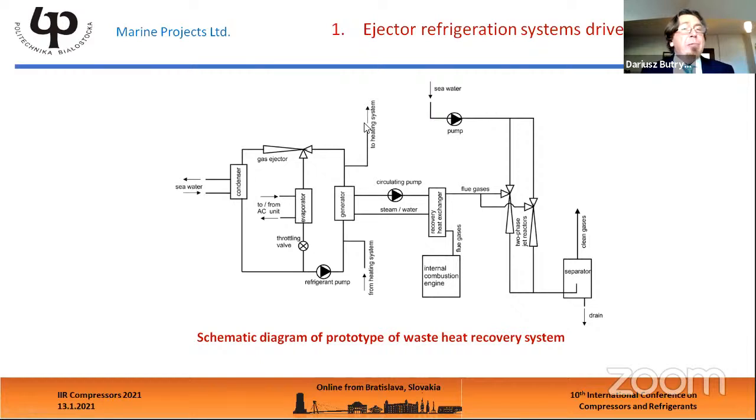So it is composed, well, we are doing the entire exhaust system. This system is composed of a diesel engine, and first we should build a waste heat recovery system in order to recover the waste heat from the flue gases. In our case, maybe it is a unique situation, but we have applied a water steam recovery system. It is really operating in marine applications, because due to safety reasons, you may not apply just flue gases to drive the system directly. And this is our ejection refrigeration system. It is our design of waste heat recovery system.